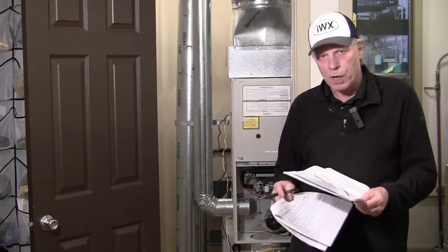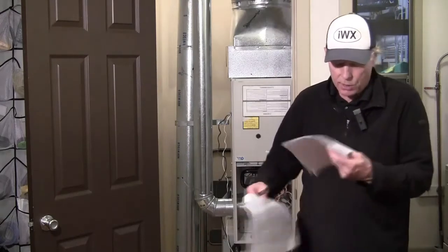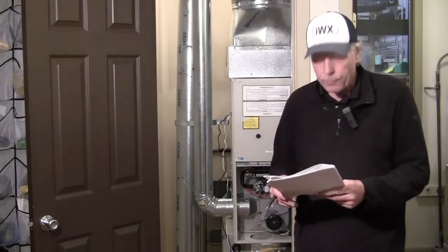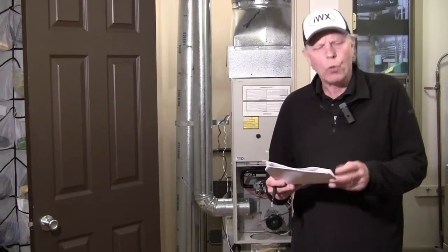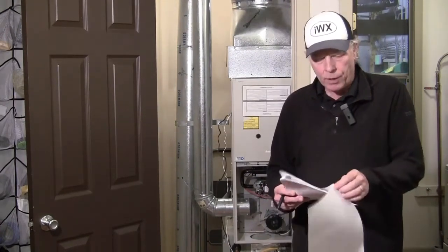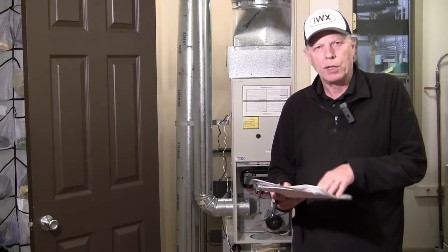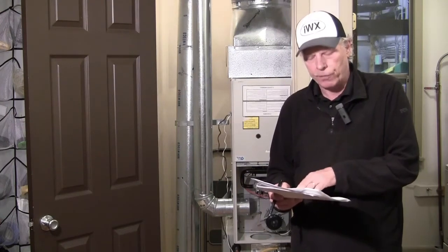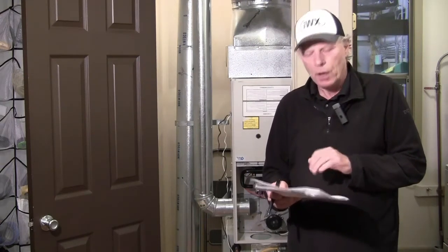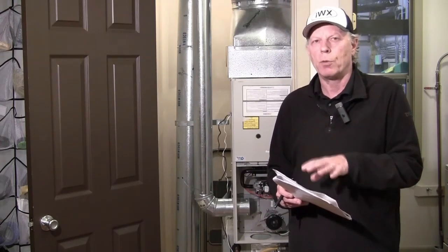As you remember from the water heater, we need to look up the CO threshold for a furnace. And that CO threshold for a furnace is 400 parts per million air free. We only had 180, so we didn't reach the threshold. So we would say we have an acceptable level. Table D1B is all about action levels and test results for CO in the flue. And since ours is acceptable, there's no action required. Again, you need to become familiar with this BPI sheet because it has all the applicable standards for the test on it.